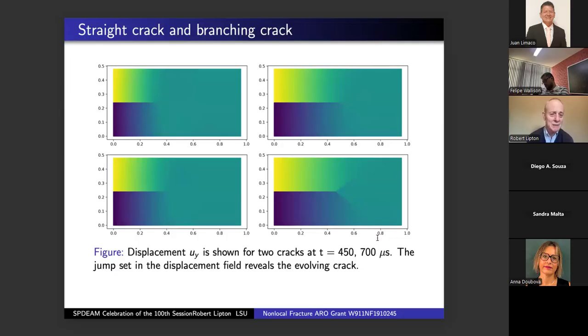But behind the crack tip, it's not. It is cracked, and this sort of releases energy. There's not as much energy anymore. It's sort of the shadow of the crack tip, and now we don't have so much stress in the top part or the bottom part of this panel. So the stress between here and here is much less than the stress here, but we crack to relieve the stress. And here, if we pull on it too hard, the crack could be unstable and split into two.